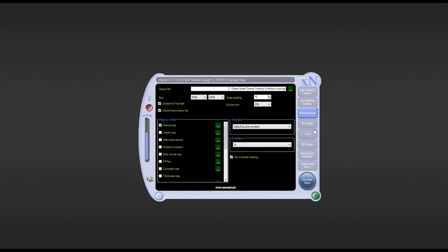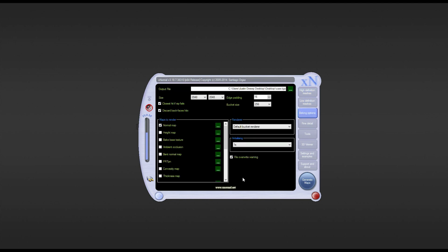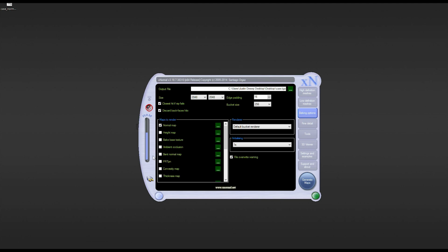So now that we have everything set up here, the next thing we're going to do is go ahead and do the bake. So I'm going to quick pause. We'll go ahead and bake it out because I kind of want to show you what it's going to do while we're baking. So we're just going to click Generate Maps. One thing I might also mention, right up here under Notify Tile Updates, if you don't have that turned on, it'll just stay solid. But if you want to actually watch this thing being rendered out, that can be changed right here. But here's a rough rundown of the normal map. And what I'll do next is upload this into Toolbag and check it out.